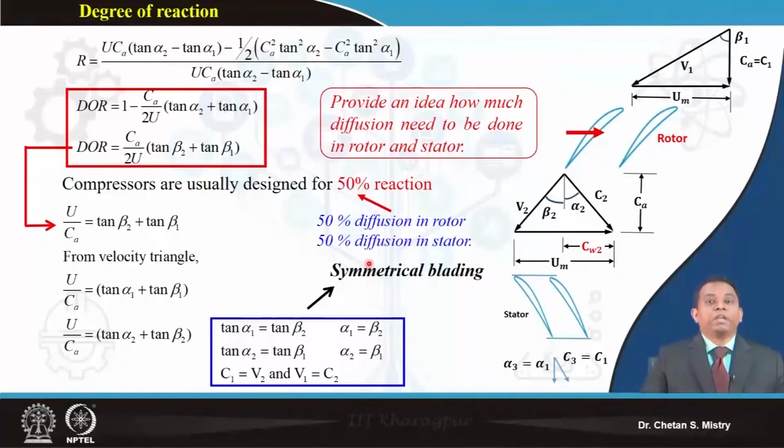Now let me tell you, when I started the discussion on the construction of the axial flow compressor, we discussed that the purpose of my rotor is to convert kinetic energy into potential energy, or we can say to give rise to my pressure.